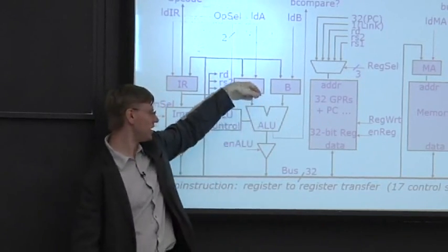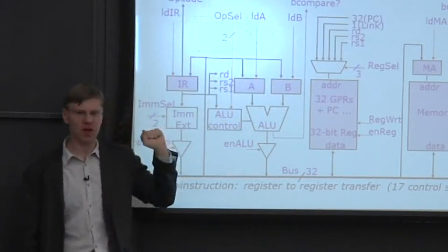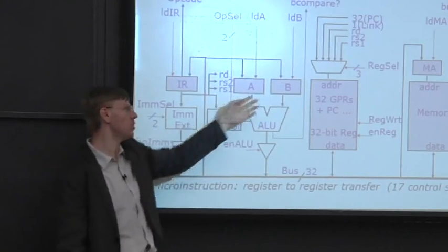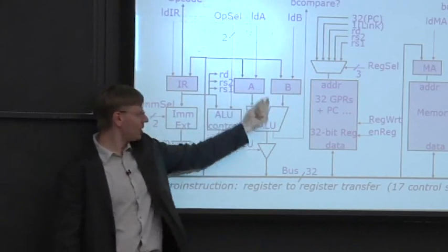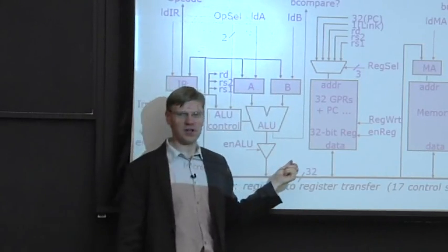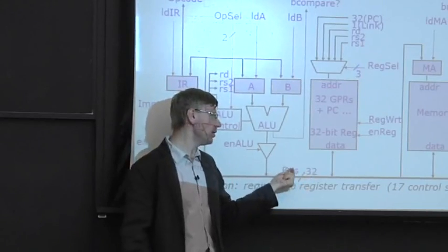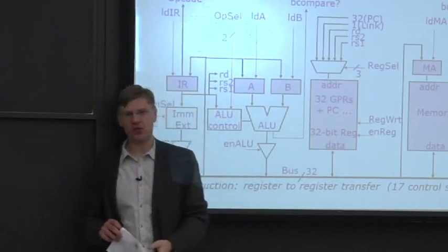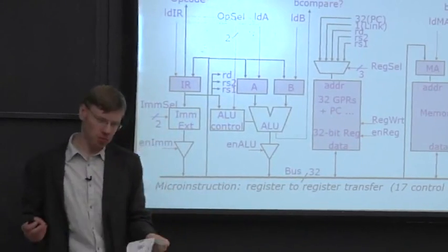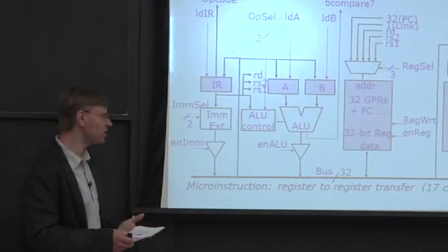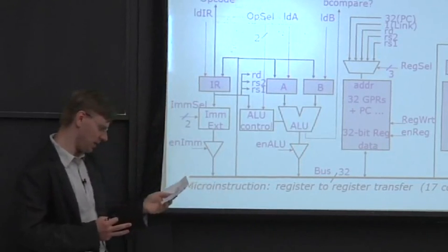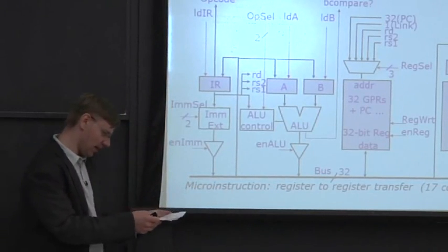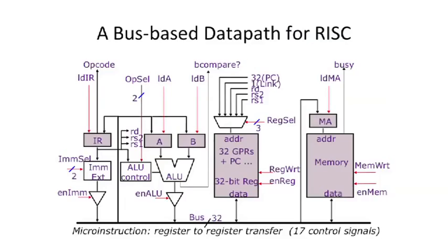So the next cycle we'll do, let's say, an operation here. Let's say the ALU has a special operation just for adding 4. Alternatively, we can try to load 4 into the B register here. And we're going to add 4 because our instruction is 4 bytes long, and we're going to store that value back into the program counter. So at this point, we've actually executed one complete instruction. And it takes, I think we added up something like 6 or 7 cycles at that point.